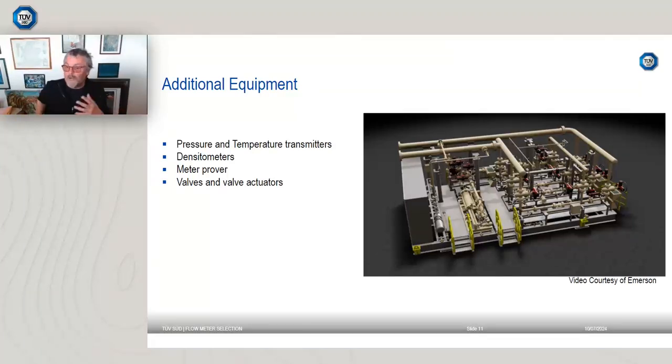And the inconvenient truth of the matter is, valves are heavy, valves are expensive, especially if they're made of some exotic material, and valves need maintained, and they weigh quite a lot. So again, this has to be borne in mind when we are making a meter selection decision.